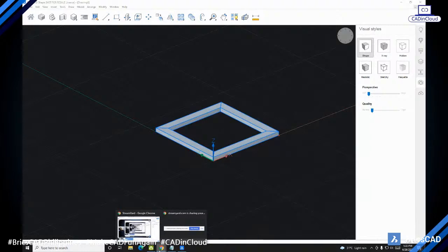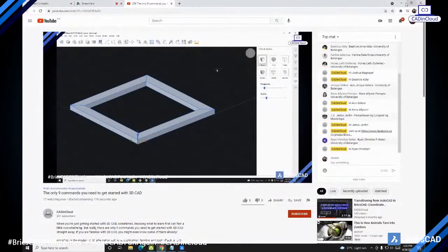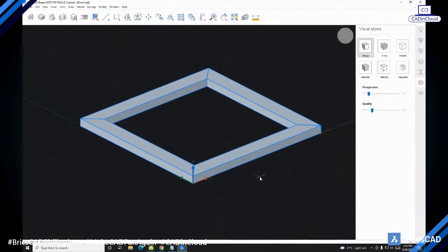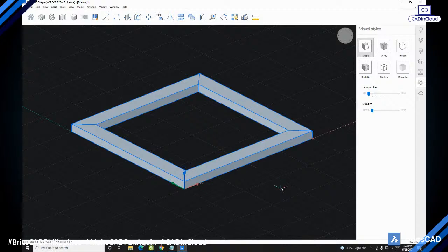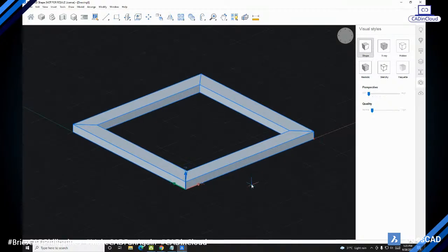Okay, let me check first. There you go. But as I said, we will be using the displacement method. It's much better for us to use the displacement method so you know some mathematical concepts in BricsCAD. This is also applicable in other CAD software. So we're going to tap letter D or simply press enter to accept the default option of displacement.